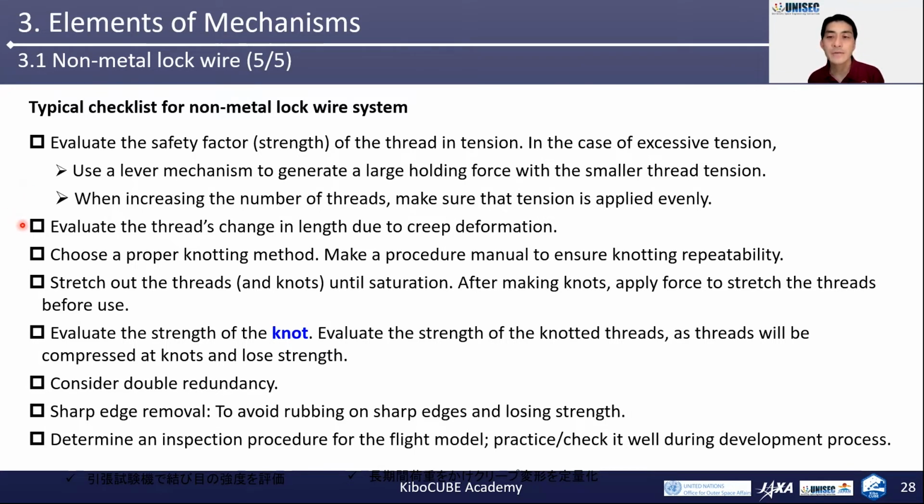Please evaluate the threads' change in length due to creep deformation. And please choose a proper knotting method. Please make a procedure manual to ensure repeatability of knotting. And stretch out the threads and knot until saturation. After making knots, please apply force to stretch the threads before use. Please evaluate the strength of the knot.